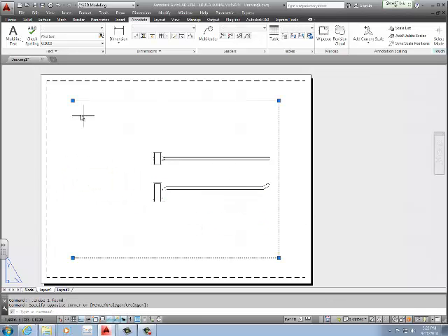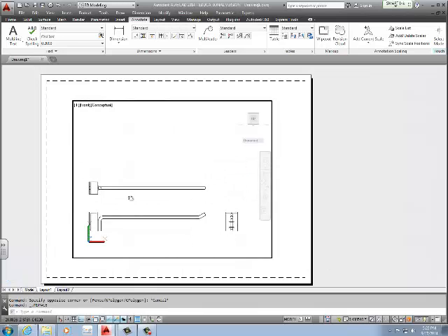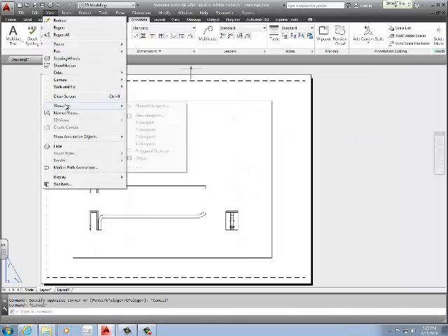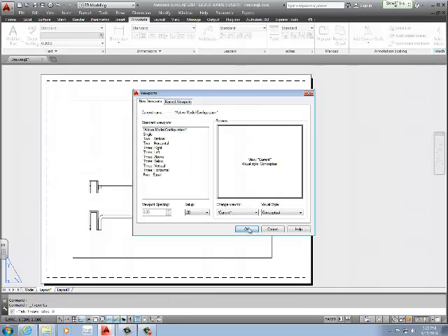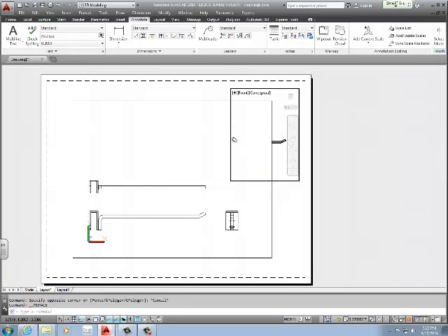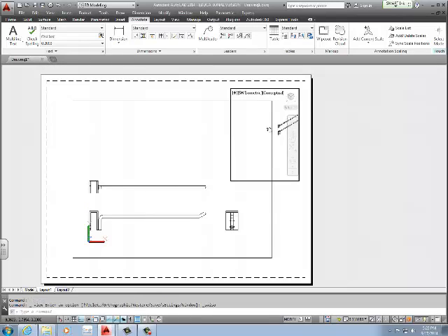So I would have two viewports. That way it doesn't have to be perfect. The idea would be to design the main viewport, which has all the 2D drawings with dimensions, and I would also have an additional half viewport, 0.5, with the 30-degree angle, which you can control, that would have the 3D parts. To create that 30-degree angle, here I would actually go into an isometric view. Now, hopefully, you extend that 9 inch all the way to here, and I trim it off.